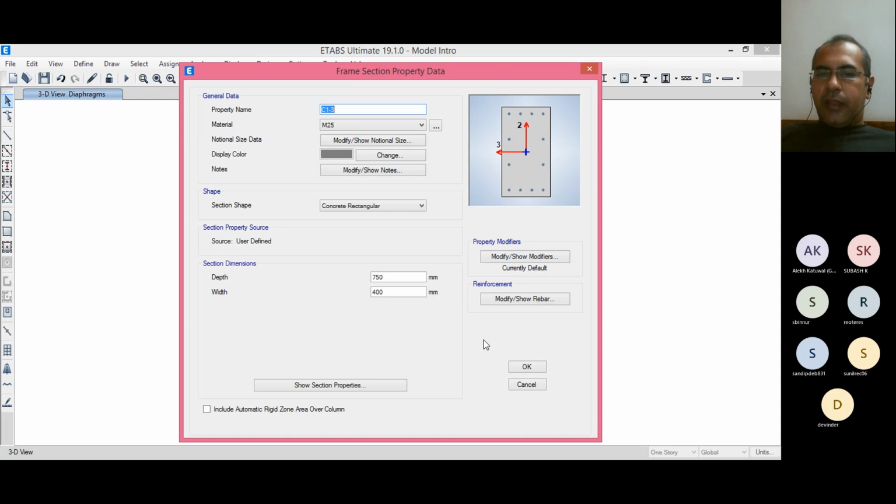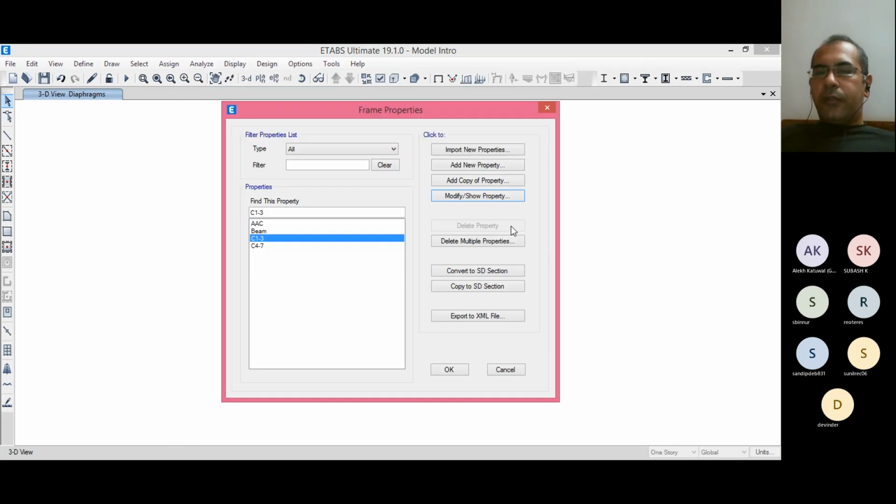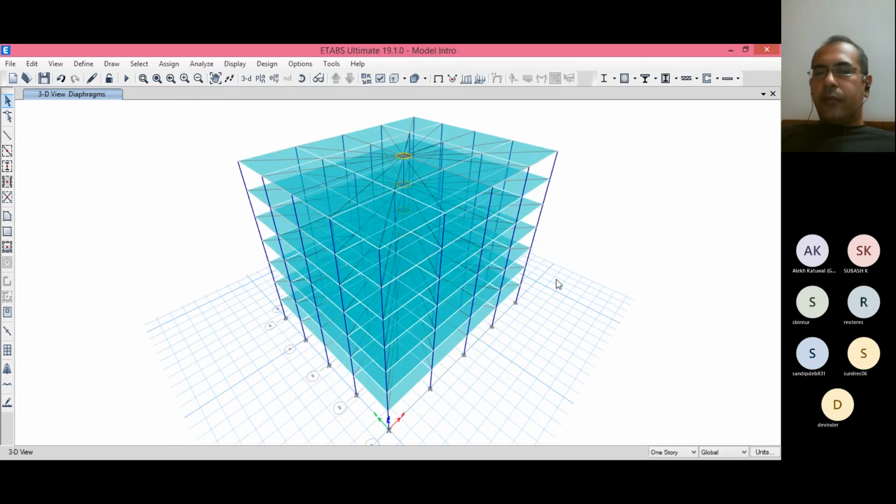So that is the I value, and stiffness will be the same, 12 times EI by H cube. So your K value K1 will be 25 into 12 EI by H cube. Right now all columns are of the same size. Similarly, if they are of different sizes, then 12 EI by H cube of different columns has to be done. Just hold on a second. Okay, fine.